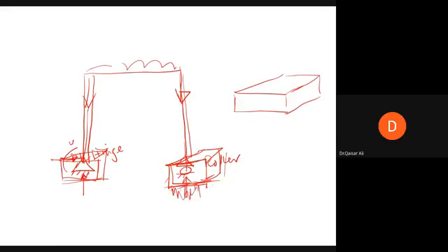the bending moments, whether this pad is able to resist some kind of bending moment or not, will depend on the size of the pad. If the size of this pad is very large, then of course it will offer some bending moment resistance, and this can be treated, instead of a hinge or roller support, as a fixed support. But if it cannot offer any bending moment resistance to the design loads,